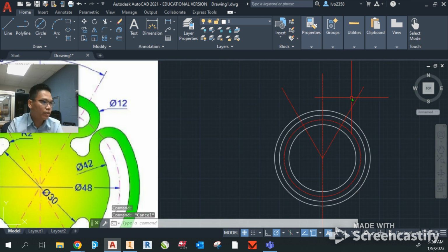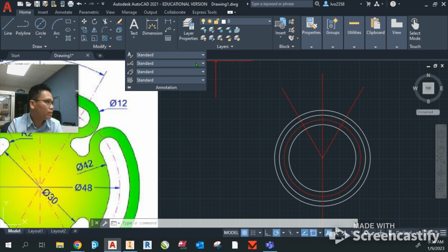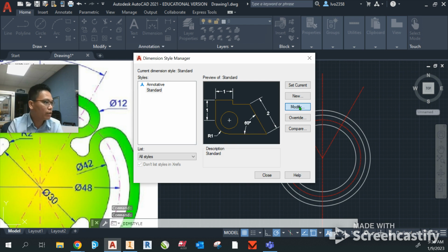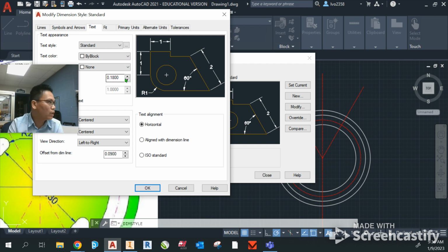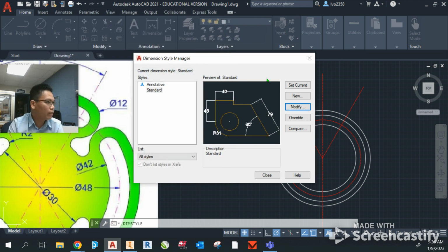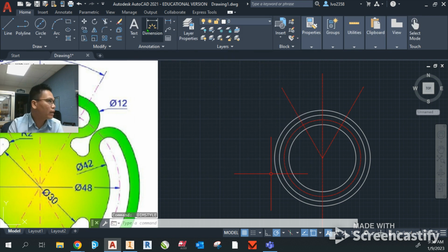So that is the basics of angle measurements, and you can go ahead and change that. Look for the measurements, and I know that we have to change the text size here real quick to make it bigger. So right now, our text size is 0.18. We want it to be like, say, everything was like 30s, and make it 7. Again, we don't know until we put it in to see how big they are.